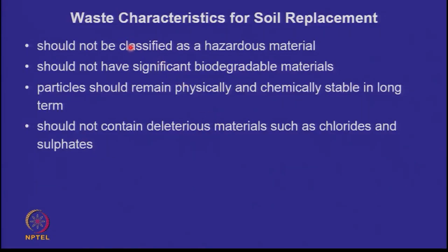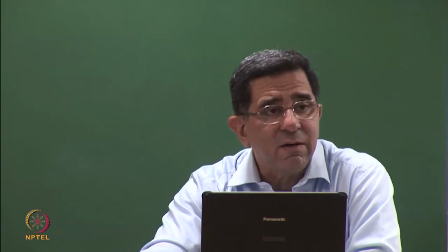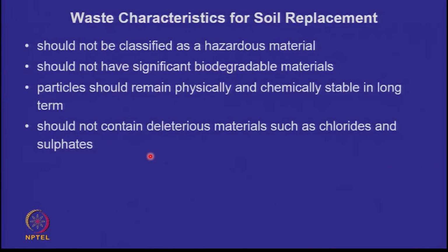It may not be classified as hazardous. As I said, suppose your waste has got common salt in it. There is no standard that soil should have less than 1% NaCl or 2%. It may not get classified. Under the TCLP procedure, you may not have any problem. But if any sulfate or any chlorides or any total dissolved salts are coming out of the material, that's not very good, because it can harm other things. So, it should not contain deleterious material.